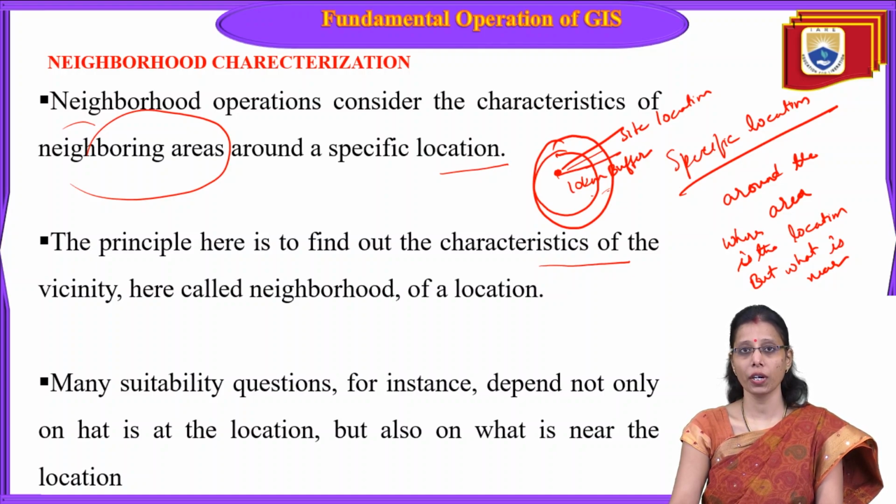Then you can see the overlay. Overlay operation is very important in the GIS process. It is possible when the GIS has some georeferencing, like latitude or longitude or some kind of location assigned to the layers. Then you can go with overlay operations, overlaying any feature on another feature. For example, you can overlay a point feature on a polygon feature, a line feature on a polygon feature, or a polygon feature on a polygon feature. These are the types of operations we can do in GIS.